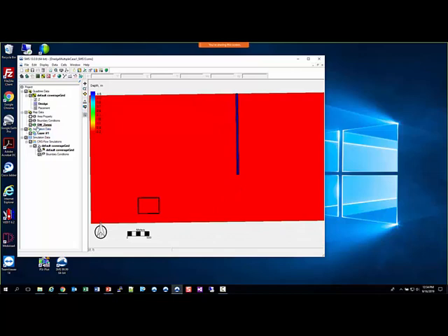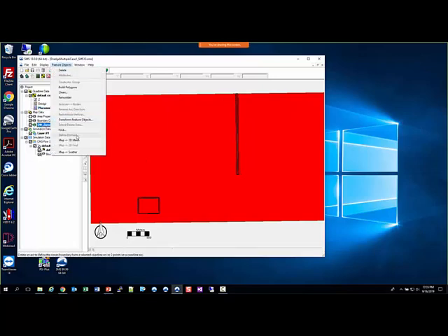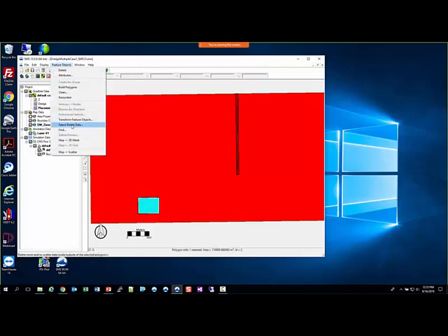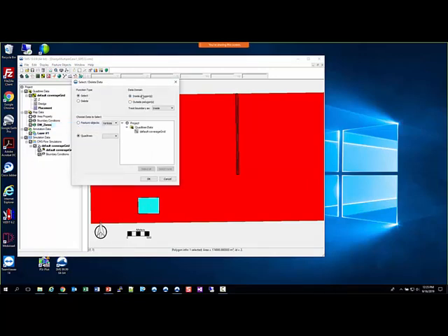All right, so the next thing we're going to do is the same thing for the placement area. So in this one, we're going to switch over to the placement. You see these have disappeared now. We go back to the map module, feature objects. Oh, I've got to select the polygon first. Feature objects, select and delete data. Select inside the polygon for the cells.